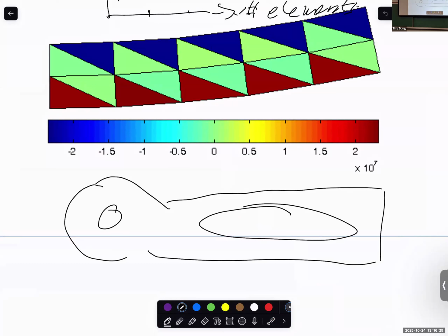So they allow you to do the partition. So you have a regular shape in each region, and then do the mesh within each region to make sure that the CST element or the quadrilateral element are not distorted too much. For the CST element, or the triangular element, we want the interior angle as close to 60 degrees as possible. For the quadrilateral element, we want the interior angle as close to 90 degrees as possible. You don't want to distort it too much. Otherwise, there's no point to do FEA. It will not give you an accurate result anyway.